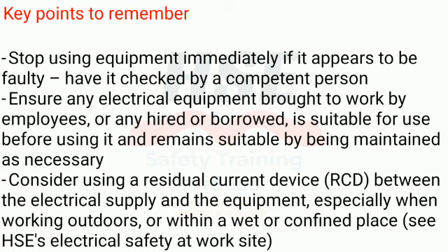Ensure any electrical equipment brought to work by employees, or any hired or borrowed, is suitable for use before using it and remains suitable by being maintained as necessary. Consider using a residual current device, RCD, between the electrical supply and the equipment, especially when working outdoors, or within a wet or confined place.